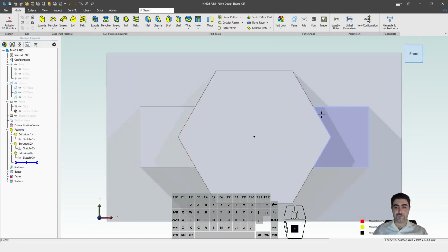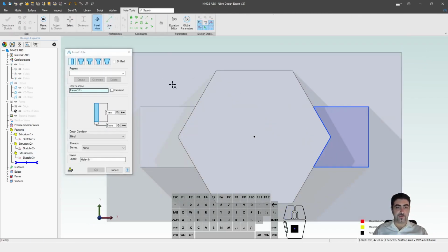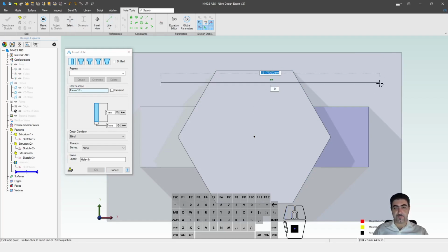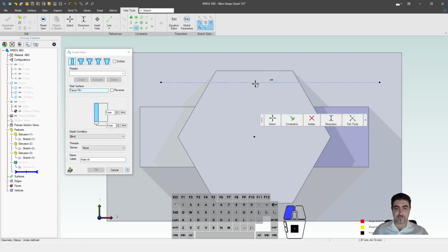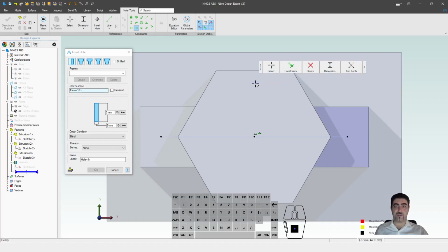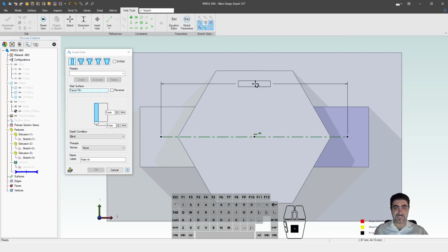Now here I wanted the holes, and you just throw a line in there. Oh, sorry. You see, you need to click the line first. So let me select that and delete it. Immediately go for the reference line, right? Make sure it's vertical. And here you can do it 2 ways. You can just hit 150 here. What I did in the actual entry is I clicked on the line, hit M, made this the midpoint, and without touching the mouse, right? Touching the mouse loses you time, hit D, enter, 150.